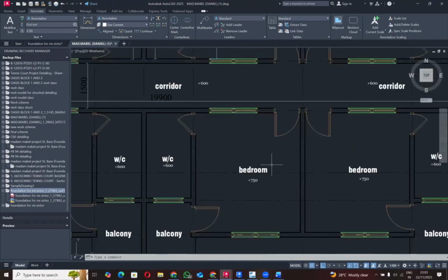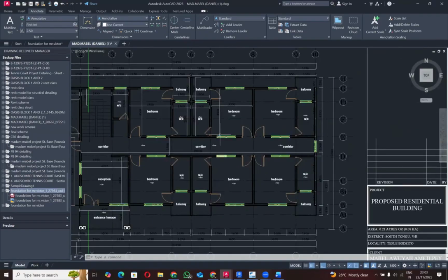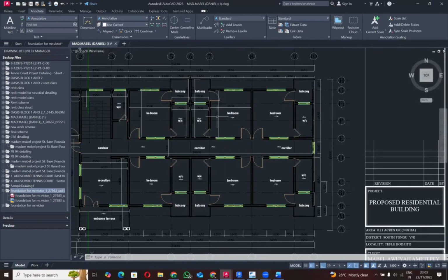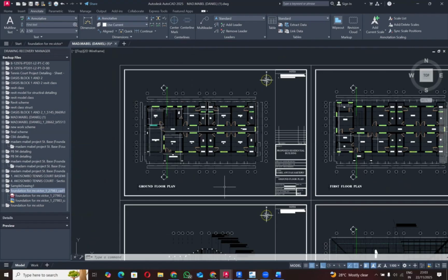And you have to put together a model that meets those architectural elevational differences. You also have to look at your structural requirements, where you focus on what the designer has given to you. So the designer has given you all the structural elements, their sizes, and also the detail requirements, which include the reinforcement type, the count number of each of these reinforcements for each of the structural elements, and then the spacing that you have to follow through.